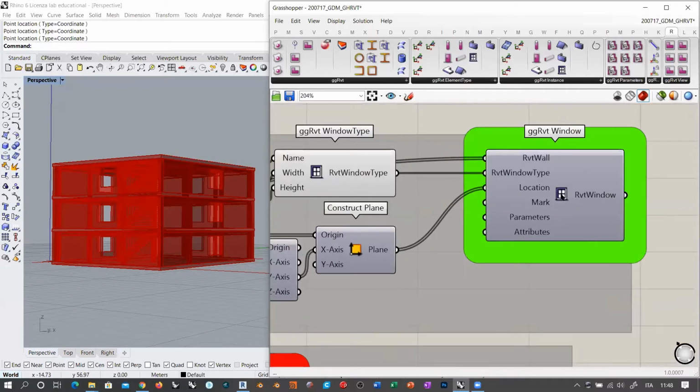The presence of the window is actually represented by this rectangle. So in Grasshopper, you don't get any 3D window, basically. You just get the hole. So the important thing is to define the geometrical aspect of the window, which means the width and height, and the family type. If you define the family type properly, once you import in Revit, you will have the family automatically recognized, and you will see the 3D elements occupying the space, the void that is being created inside here in Grasshopper.